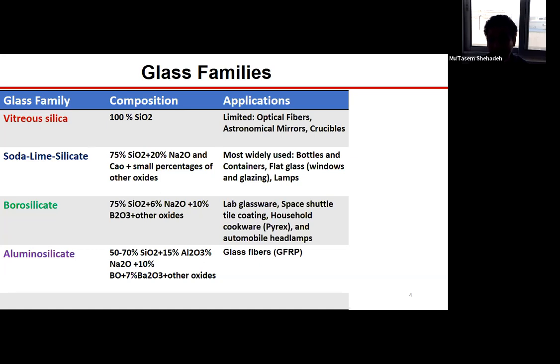This is, for example, different than when we talk about laminated glass. In laminated glass, there is a layer of PVB. It's a polymer, and this polymer will, in fact, absorb the impact energy the sample is subjected to. In the case of borosilicate and soda lime, both are brittle materials. They both fracture in a catastrophic manner. And what will determine the strength of such a structure is, again, the weakest link. Which one of those two plates has a lower fracture toughness tolerance? This will lead to the fracture of that element.